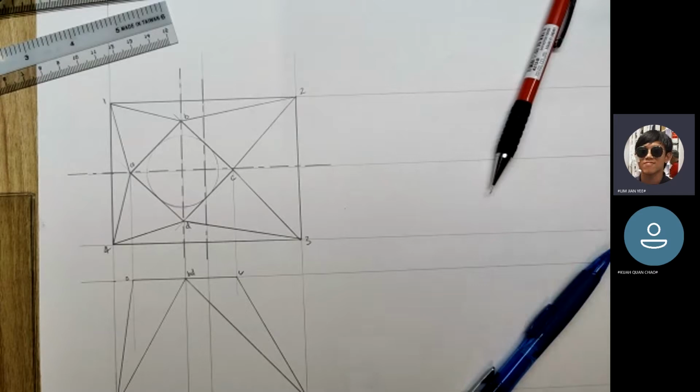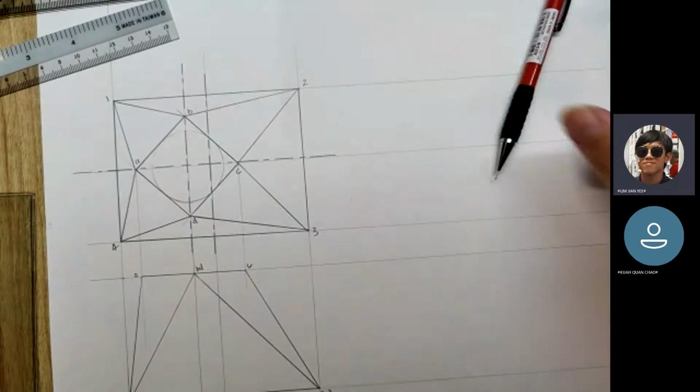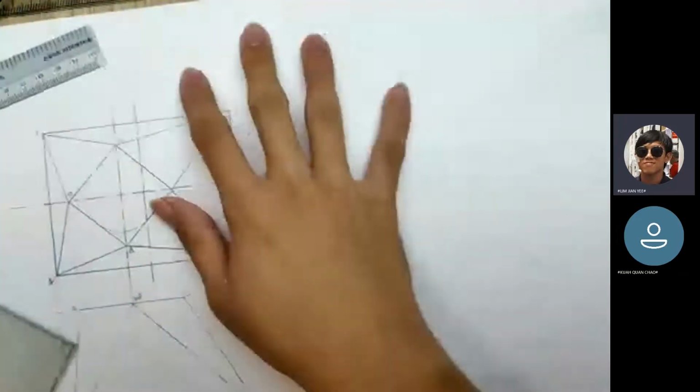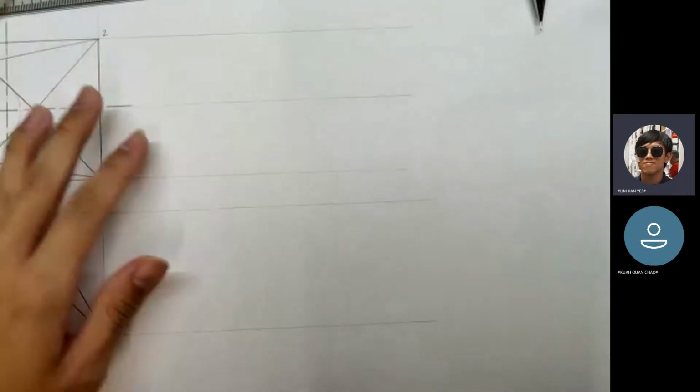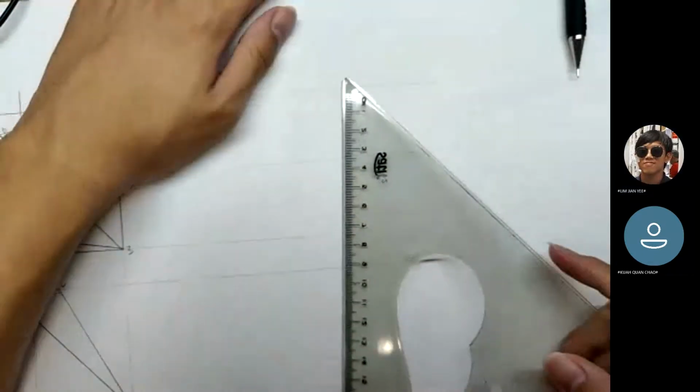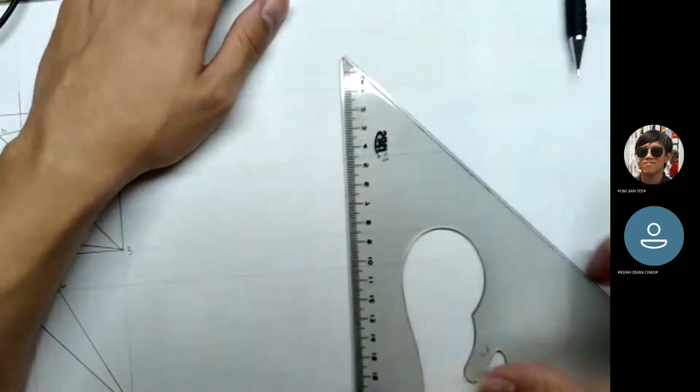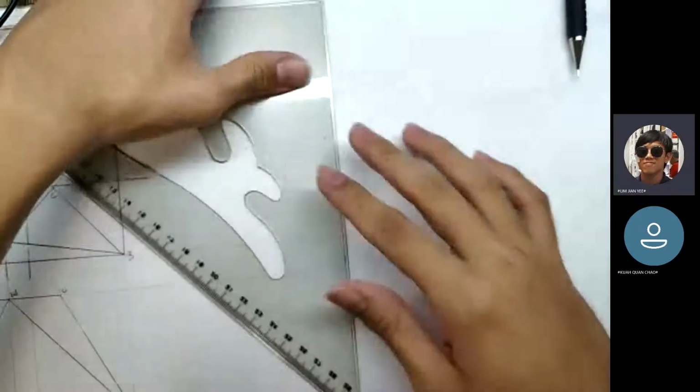Now we move on to the other part, development. Okay, so for development, generally for this shape, what you want to do is draw the development down the right side of the paper. Let me get to the right side. Okay. Then let me draw a straight line down.